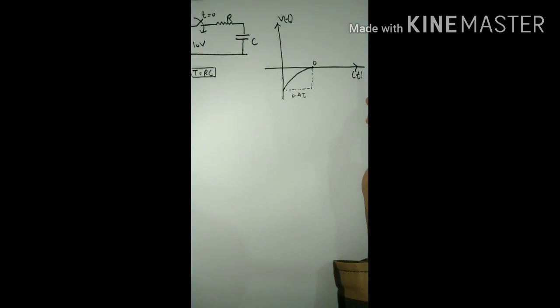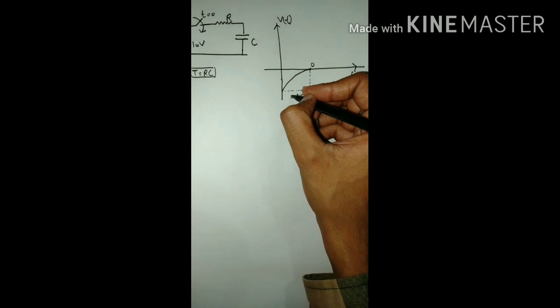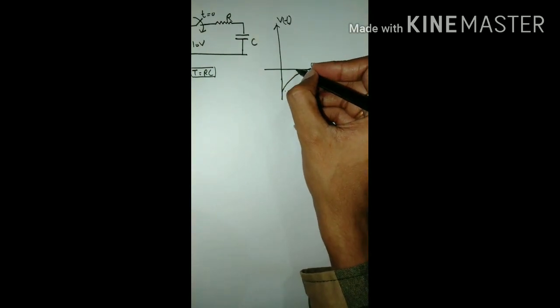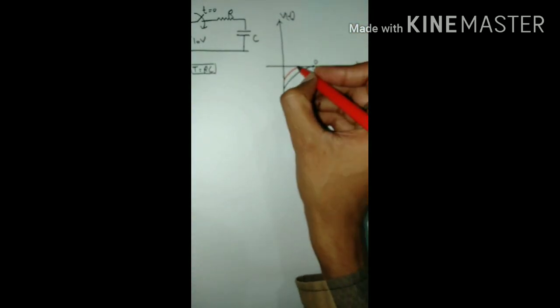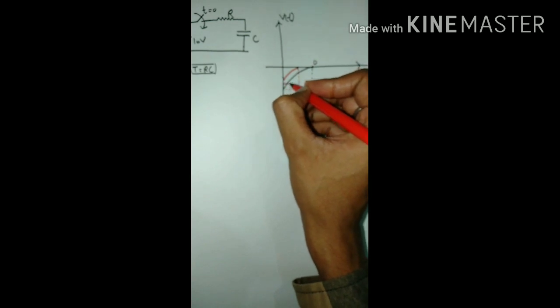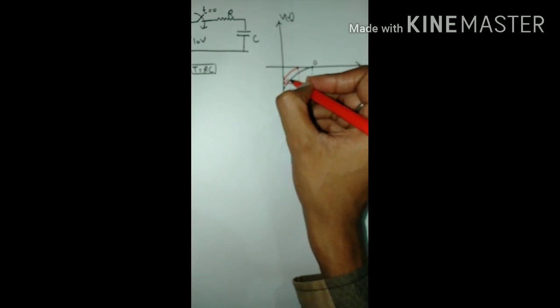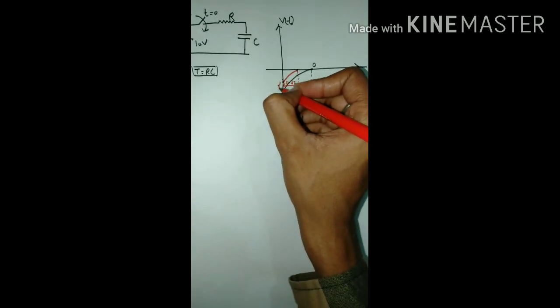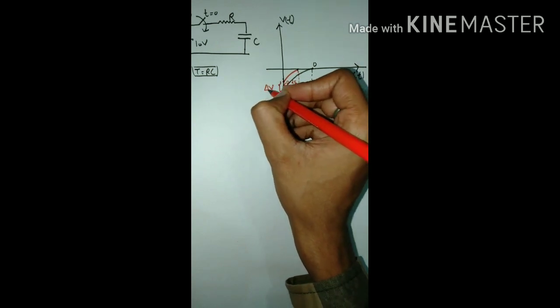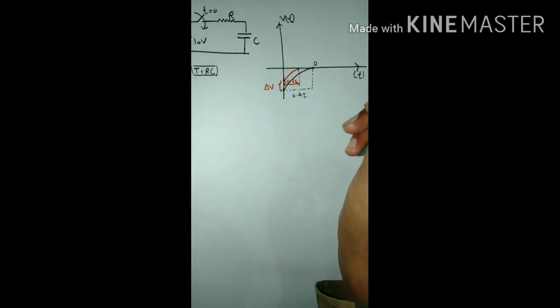What the question says is the absolute value of percentage change required in the initial capacitor voltage if the zero crossing has to happen at t is equal to 0.2 tau, means 0.2 tau is earlier than 0.4 tau, somewhere here like this. So we have to determine this change. It is not in percentage, it is the absolute value of delta V.